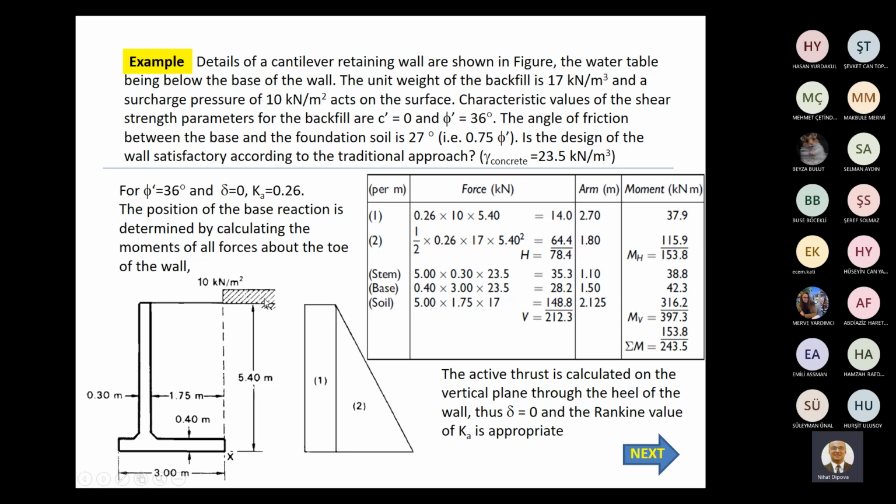We have a surcharge value above the soil. And this surcharge is used as a rectangular distribution, it doesn't change along the depth. And this rectangular element is used for this surcharge. For resisting moment, all the weights of the cantilever wall and backfill play a role for resisting.